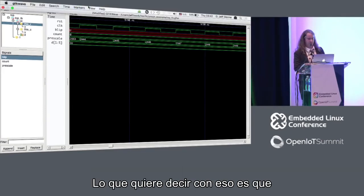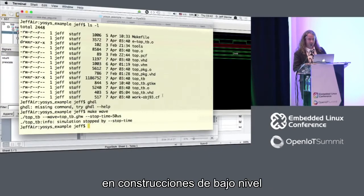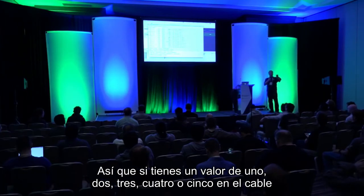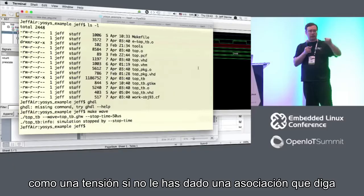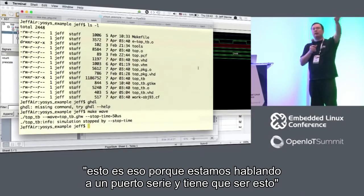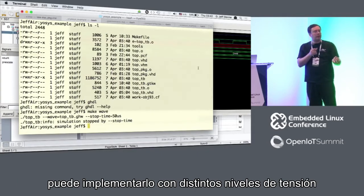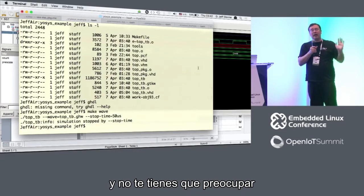What he means by that, there's a stage called elaboration where it turns higher-level constructs into lower-level constructs. It's sort of like an optimizer in a compiler. So if you have a value 1, 2, 3, 4, or 5 that's on this wire, it's up to the compiler to figure out how to represent that as a voltage if you didn't give it a binding to say this is that, because we're talking to a serial port and it has to be these. Internally, it can implement that as a bus of multiple wires if it wants to. It can implement that as multiple voltage levels. It can implement that as a serial encoding. It can implement it a bunch of different ways, and you don't have to care.